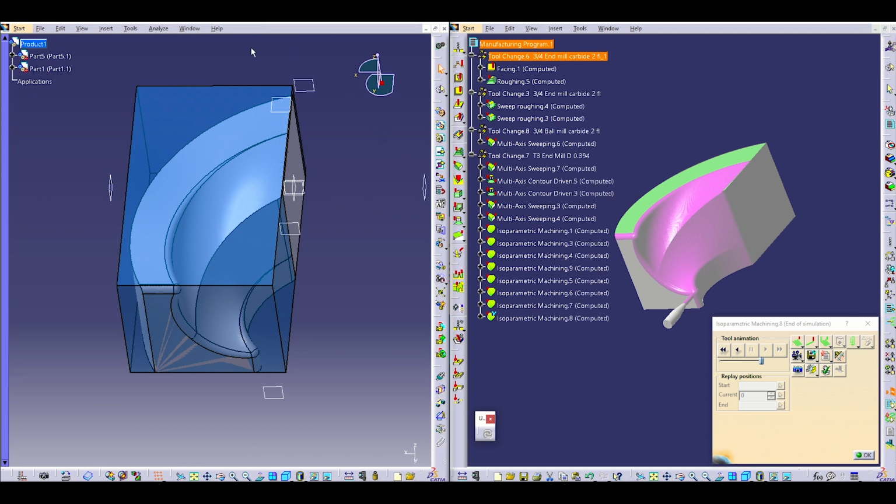To start, this is the part we've created here, with some cool little curves. But we're going to need to do something with this stock, which is a cube. We're going to need to rough down some of that excess over there, or else with some of these functions, the bit is going to totally crash into the stock and wreck everything.